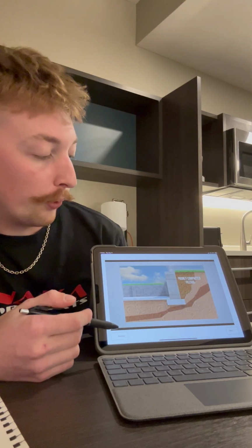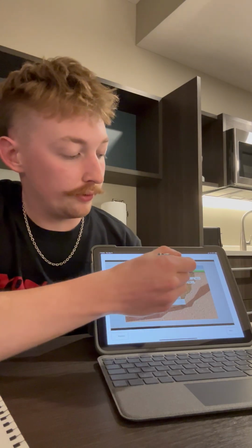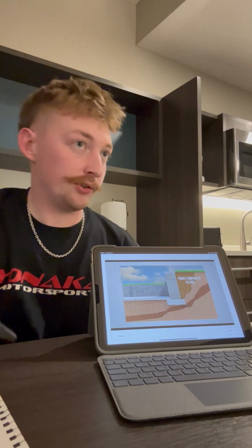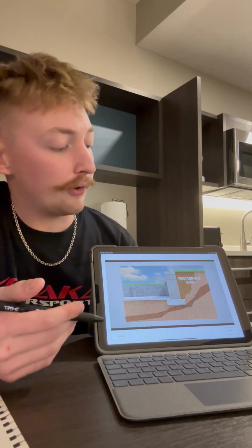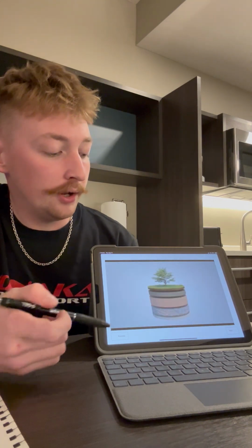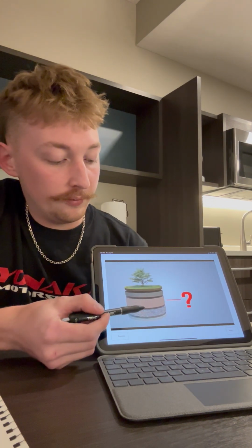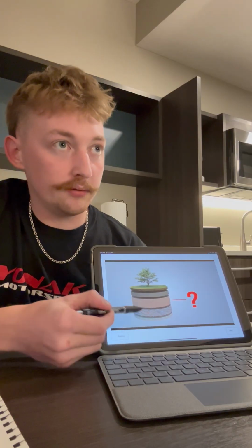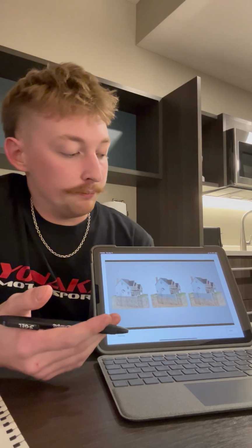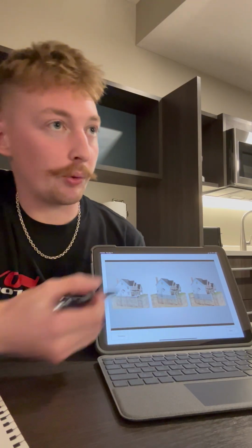Thirdly, you have poorly compacted soil. So when the foundation was actually poured, the soil, the loose backfill, wasn't compacted properly. So this could easily wash out the dirt around a foundation wall. Now, we don't really know which layer you have your house sitting on. We usually want it on bedrock. That's the most stable. And then we have here, just again, 3 different types of settlement.